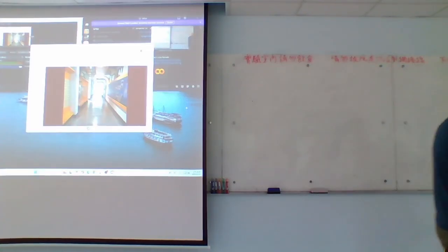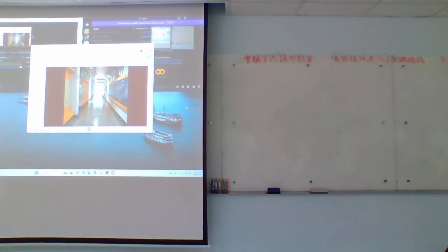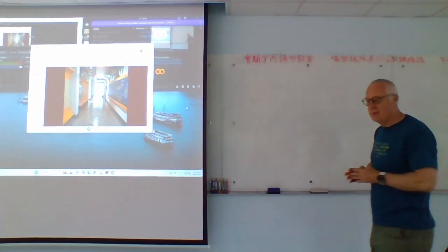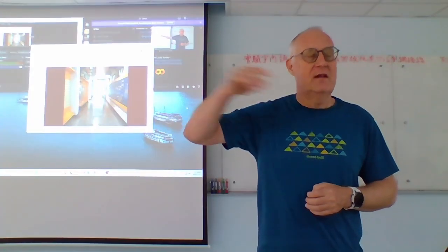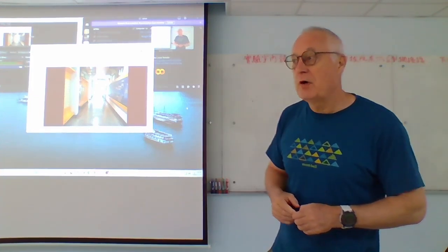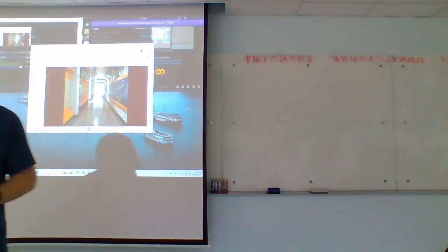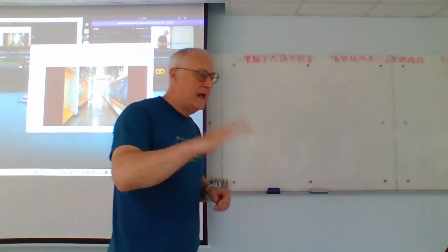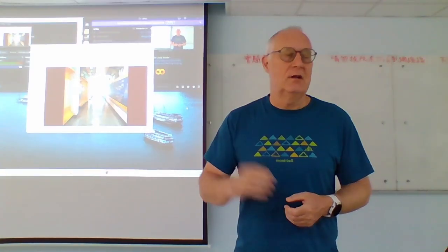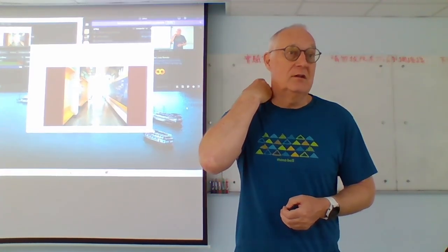And there are some applications that are like that. So for example, with the scooter project that we have for our humanoid robot that drives the scooter, one of the crucial problems was that the control very much depends on the lean angle of your scooter, of course. That one we can measure quite easily, but it also depends very much on the current velocity that you're driving at.